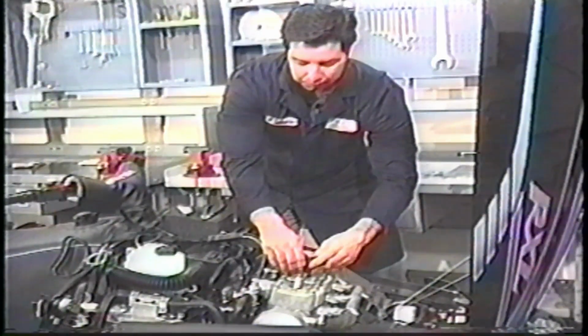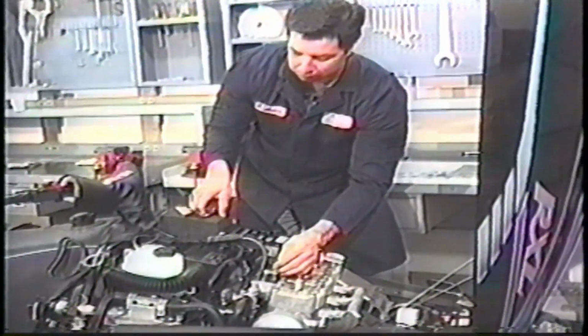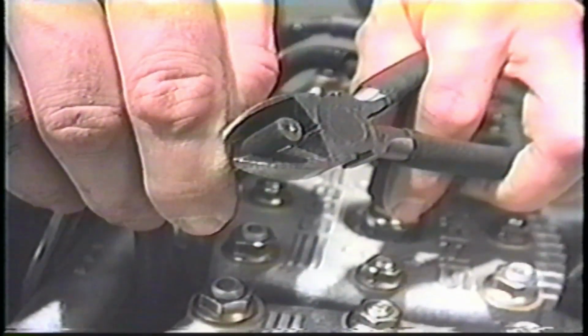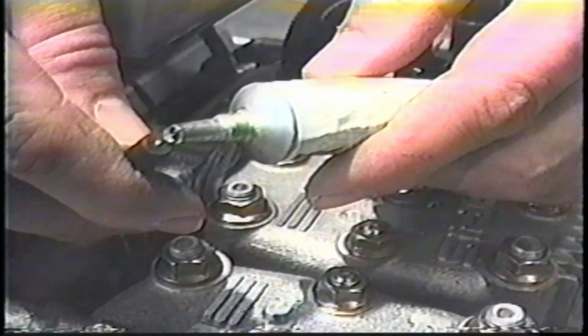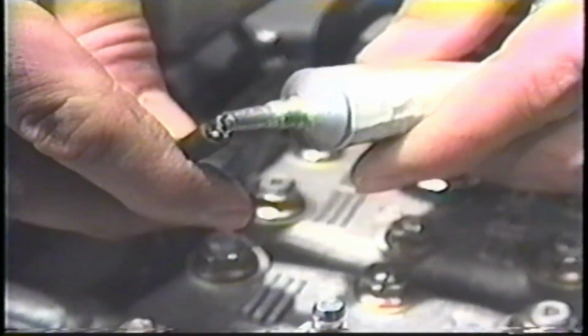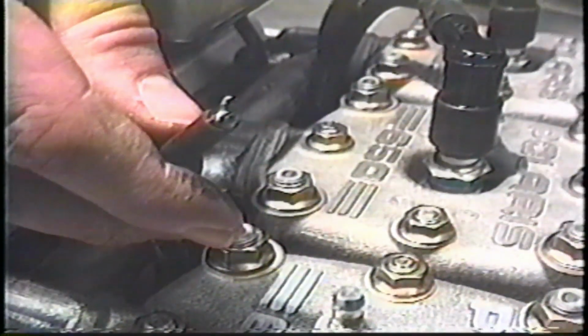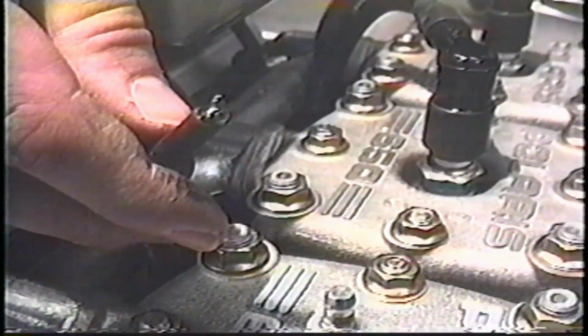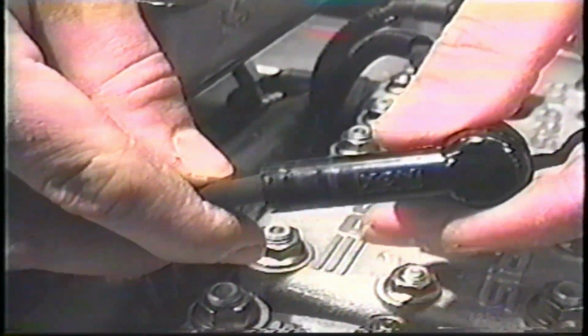Remove the spark plug caps and check for corrosion. Remove 1/4 to 1/2 inch from the end of the high-tension lead and make sure the cap is securely fastened to the high-tension lead. A light film of dielectric grease will ease installation and help seal the cap. A loose, corroded, or wet plug cap may cause intermittent ignition problems as well as a weak or no spark condition.